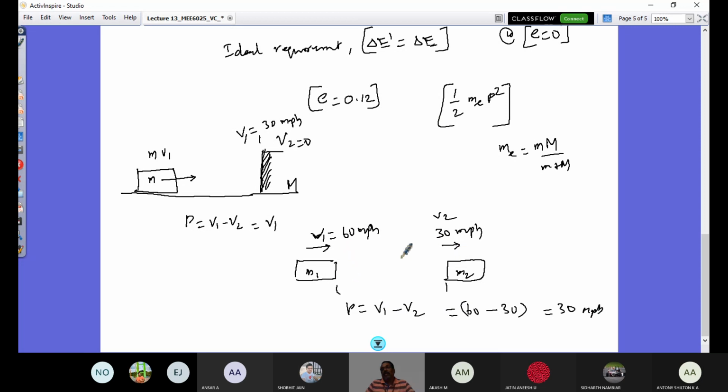The speeds may be different. So if this vehicle goes with 60 and this vehicle goes with 90, the relative velocity is the same. The energy dissipation is the same. That's what you should understand. The speeds may be different when they collide, but the relative speed is the same, and that would come here and it would affect. And this ME is not one vehicle mass, it is an equivalent or effective mass of the two vehicles, and that would be given by this. In this case, ME is M1 M2 by M1 plus M2. So it's very interesting, the concept of effective mass consideration in collision.